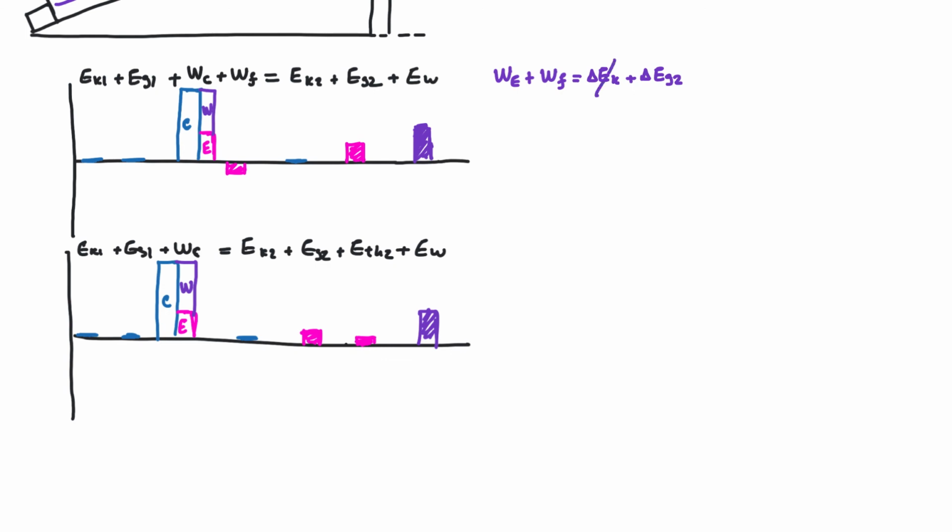Change in kinetic energy in this case is 0. We know that already. We can go ahead and write this as the work of the engine, which we don't have its value for, plus the work of friction, which we don't have its value for, is going to equal the change in gravitational energy, which is gravitational energy at stage 2 minus stage 1. At stage 2, we have some gravitational energy, but at stage 1, we don't have any, so I'm just going to write this out as mgh2. You can also just write it as mg delta h.